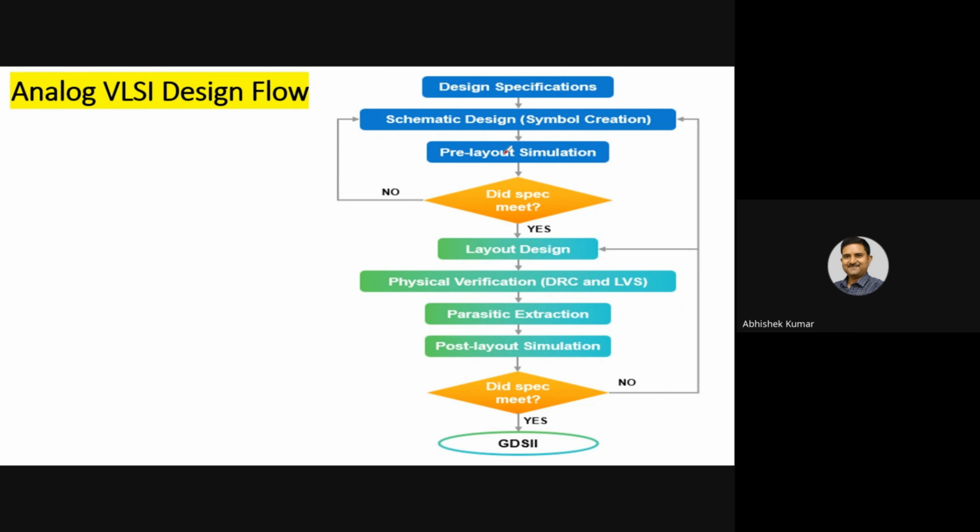schematic design. Like in digital design we talk about RTL coding, programming with Verilog. Here the same step is the designing of the circuit at transistor level, which is called the schematic. Then we can go for simulation, which is called pre-layout simulation.